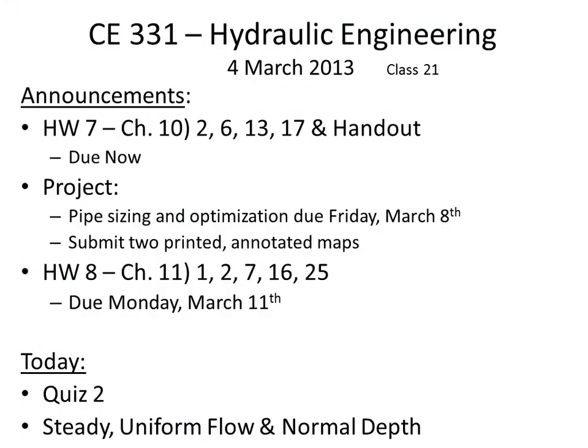Any questions on the flow demand estimation stuff that I handed back? By Friday, you need to have your first attempt at sizing the pipes completed. And the submission for that is 2 printed maps with annotations showing the pipe diameter, the flow rates, the pressures at the junction, and so on.